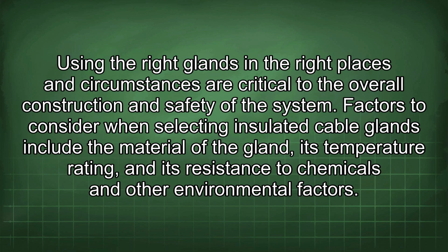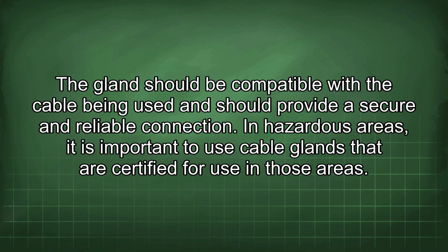Factors to consider when selecting insulated cable glands include the material of the gland, its temperature rating, and its resistance to chemicals and other environmental factors. The gland should be compatible with the cable being used and should provide a secure and reliable connection.